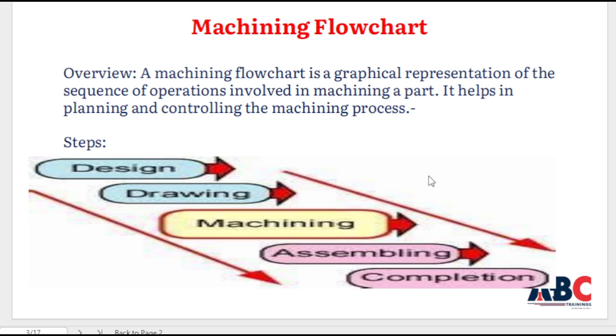Let us consider the steps involved in creating a mechanical device to solve a given problem. First step is conceptual development or product design, the designing stage. Second is draft or detail the plan for each part in the drawing stage. Then the individual parts are machined. Next, we lay out the assembly. Finally, the device is assembled.